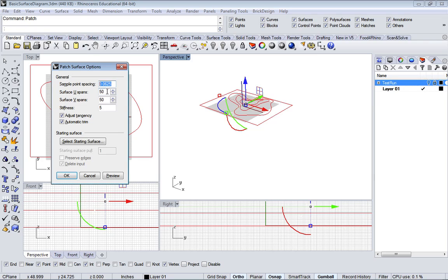But you have to be careful, because if you create too many, it could use up a lot of memory, and if you don't have a lot of RAM, it could crash. Usually for big broad surfaces, 10 is fine. When you get into topographies and things like that, 50s and 100s are probably the range you're going to want.